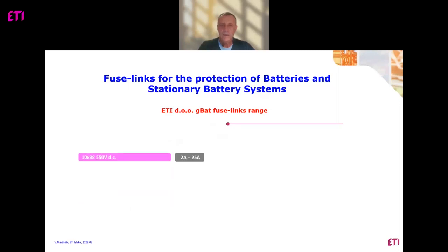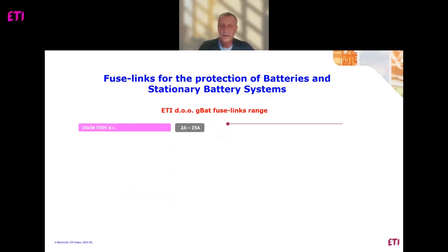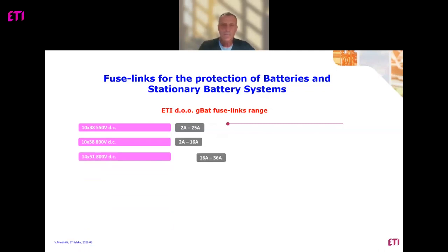ETI range is quite interesting. So as I mentioned, 10 by 38, 500 volts, 10 by 38, 800 volts, 14 by 51, 800 volts up to 36 amps.